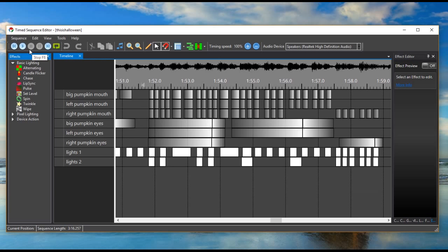Now, if you have your Arduino set up to the side with the breadboard test setup that I have in the Instructable going, and you've compiled your Arduino sketch with testing set to true, then what you'll see is your LEDs, which correspond to each one of these channels, should blink in time and intensity with the channels that you've defined here. That's way more useful to me than having the actual pumpkin set up, because you don't have to watch those. You have something right in the corner of your eye to watch for the animation. It makes it go a lot faster.